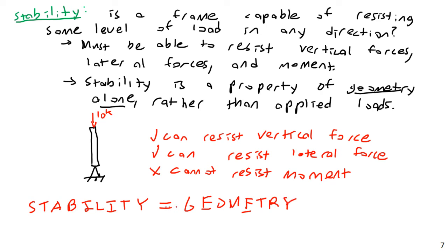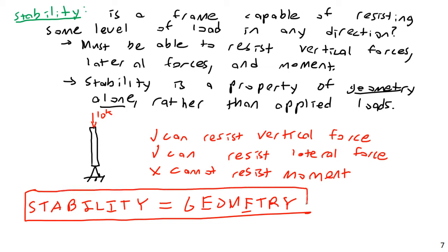We judge whether a frame is stable regardless of what loads are applied to it. And a few caveats as well here. To be stable, the frame must resist not only motion, but changes in internal geometry.